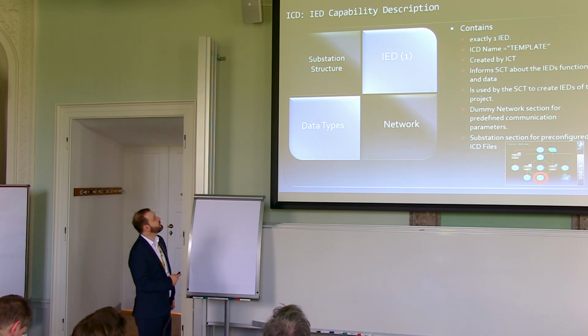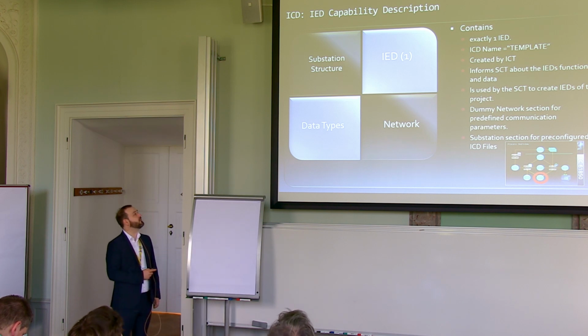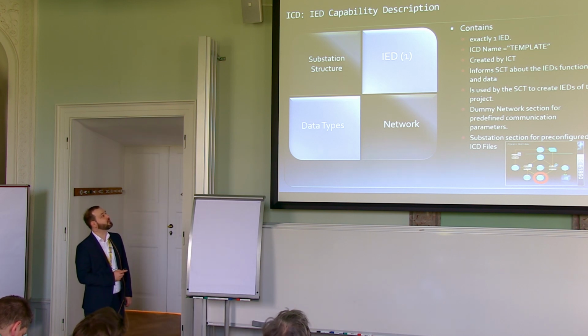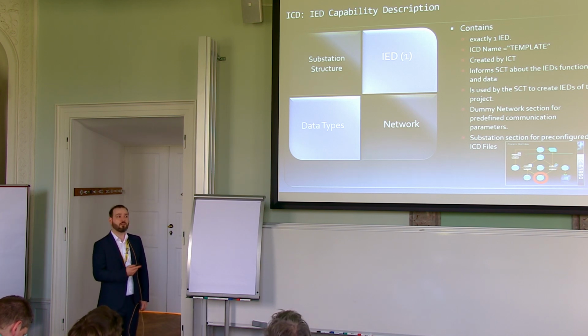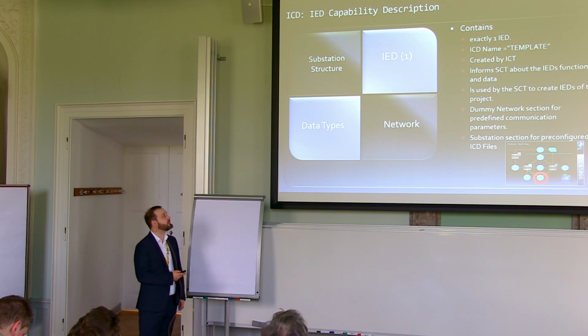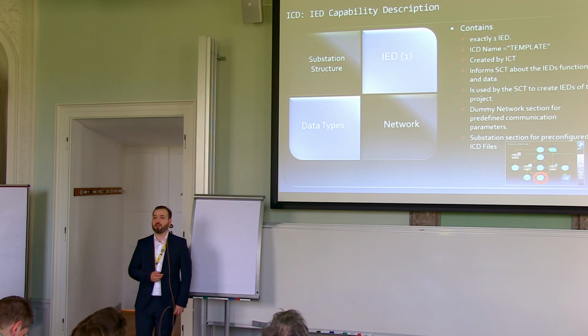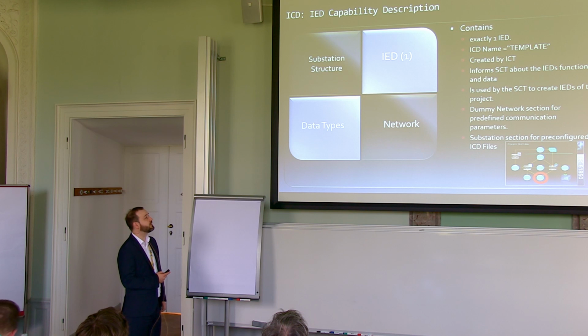So the system configuration tool can use these ICD files to create instances of the IED data model in the project. And then these instances can be modified, configured, and finally be part of the substation configuration.